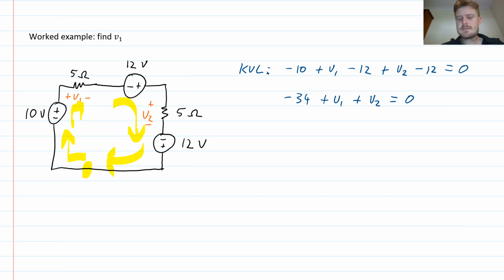The extra information will come from Ohm's law. So I'm going to specify a new circuit variable, which I'm going to call I for current, and that will be the current flowing in this loop. The current in a loop like this is the same everywhere in the loop. Kirchhoff's current law tells me that. I could write, in equals out for every single node, and they would all tell me that the current everywhere in that loop is the same. So there is some current flowing here, and if I would like to calculate these voltages, then I would need to use Ohm's law.